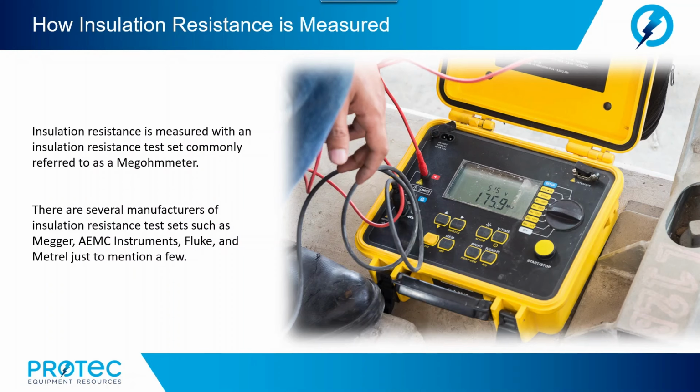Now, next, how is insulation resistance actually measured? Well, insulation resistance is measured with an insulation resistance test set, commonly referred to as a megohmmeter, and in some cases it has the slang name of megger, although Megger is actually a manufacturer, a company that manufactures insulation resistance test sets. Now, there are several manufacturers of insulation resistance test sets, such as Megger, AEMC Instruments, Fluke, and Metrel, just to mention a few manufacturers.